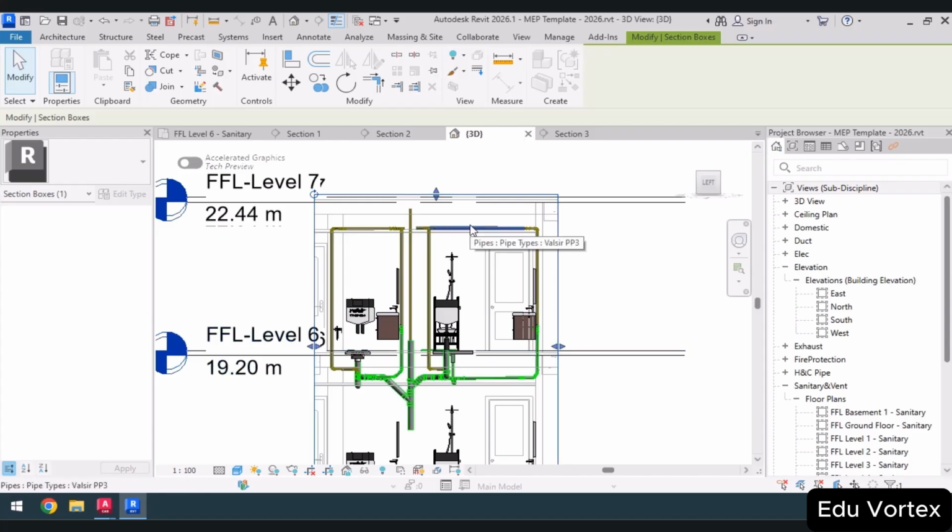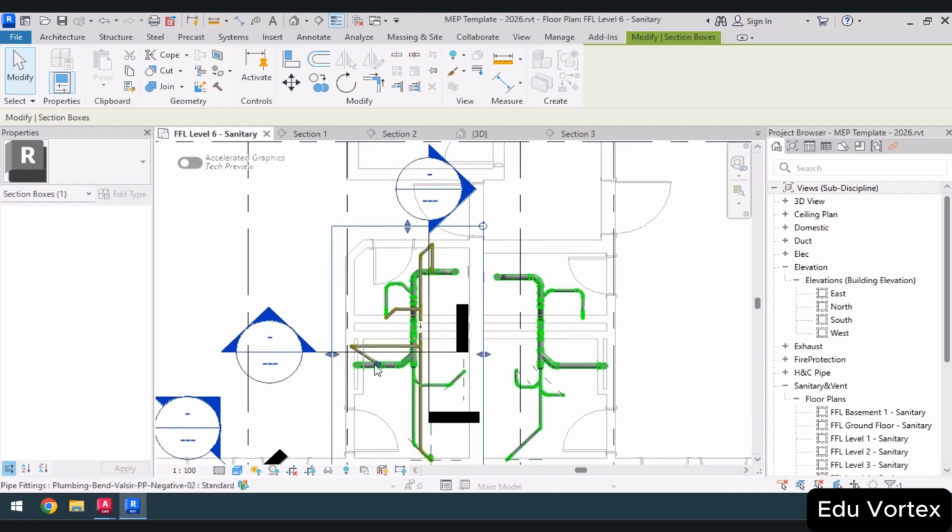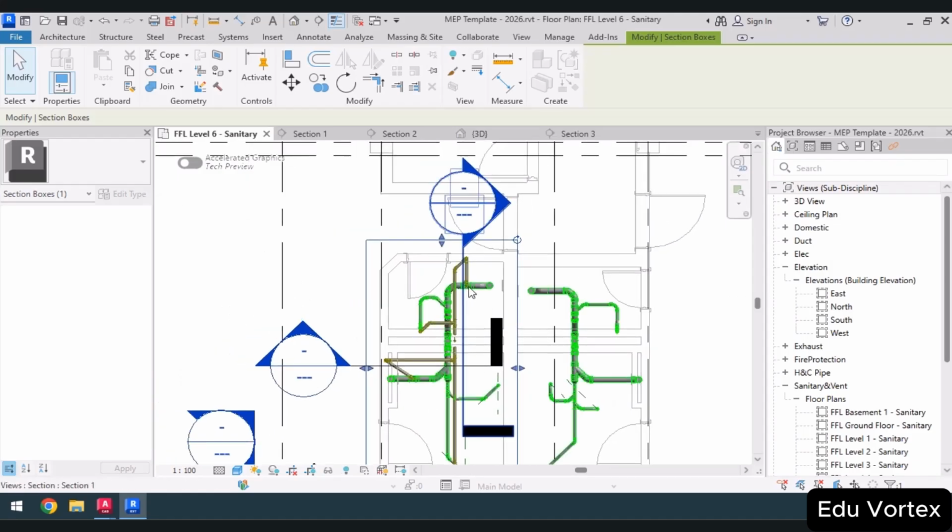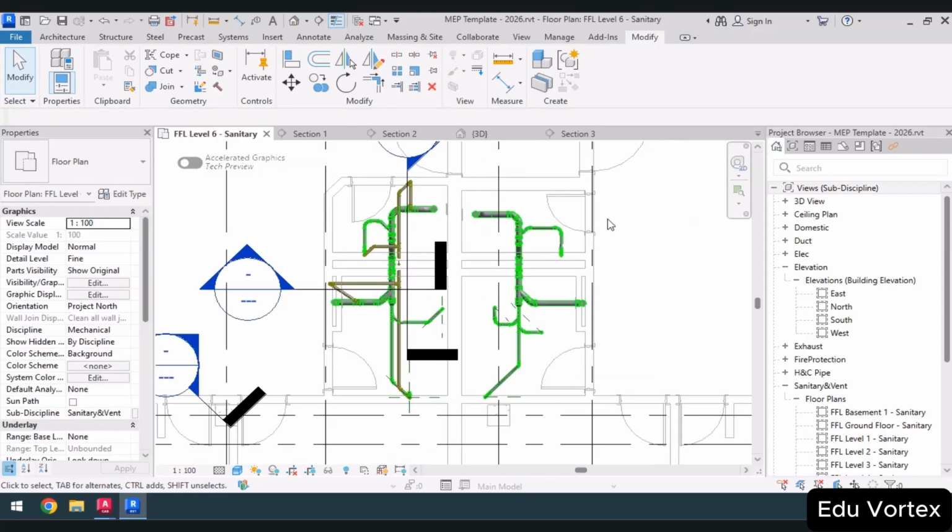First, I will draw the sinks to know where my vent should be located in the ceiling. After that, I will try to run a pipe from both the eastern and western service areas up through the wall to reach the pipe that is under the ceiling of the floor. For exercise, you can draw the vent for this service yourself. Start with the sinks, this sink and this sink, and then I will take the vents for the toilet service up through the wall until it reaches the main vent line. I will do the same for the eastern service area too.